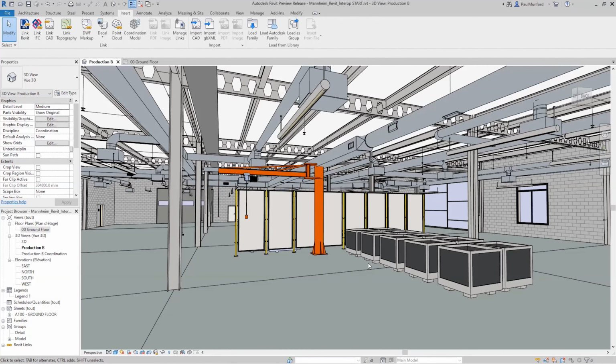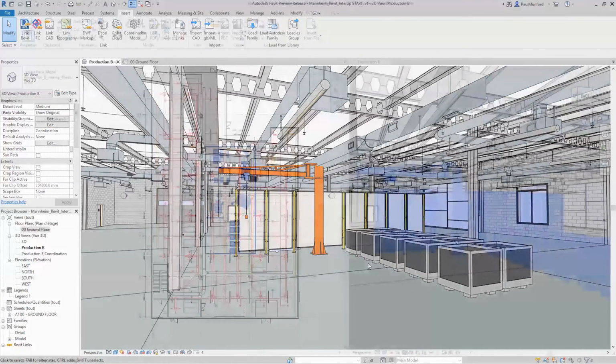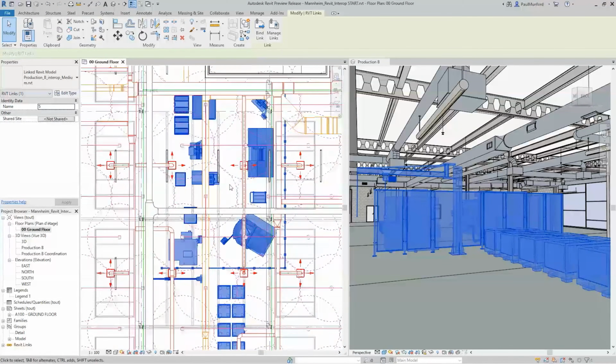And because we created this model in Inventor using the Revit model as a reference, you can see the coordinate system of the two models line up perfectly. This allows us to coordinate our design in Revit and examine it against the original design model. All the models of the other trade contractors are also going through the same coordination process. So, here is the clash we identified inside Inventor. Let's see how we can fix it inside Revit.